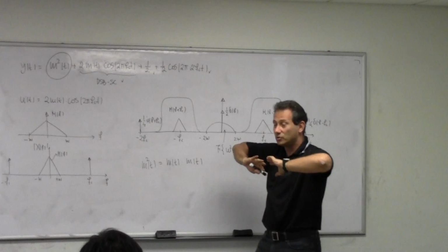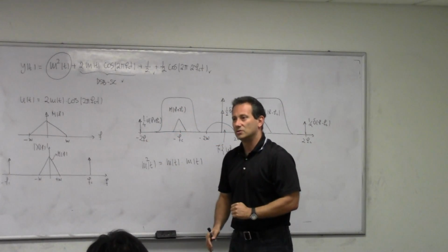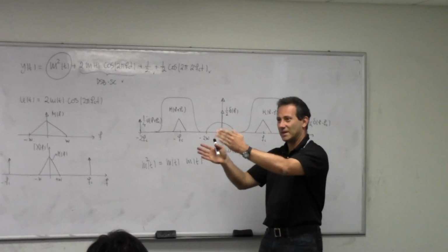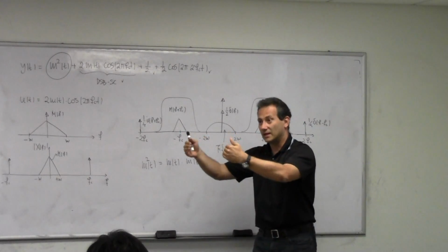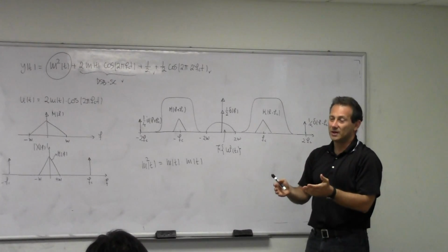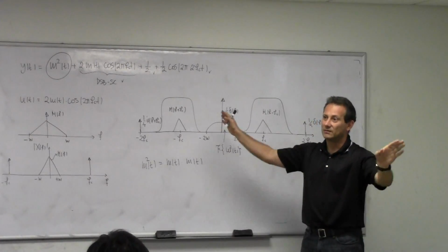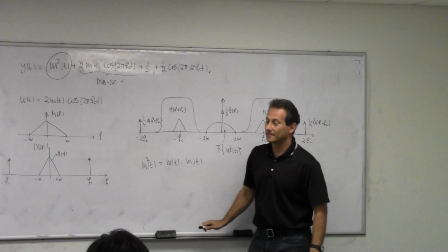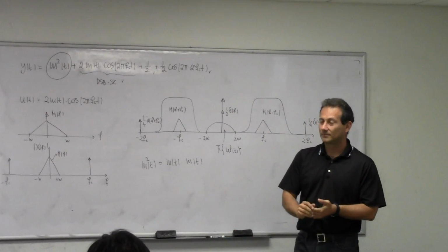So when you go towards the higher frequency, you always have the last filter as your bandpass filter. When you come into the receiver, the first filter is a bandpass filter to reject everything that is not your signal, but the last filter is going to be low pass, because a lot of times, actually all the time, you're demodulating all the way to the baseband, and then you have to reject everything that is above the frequency of your signal.